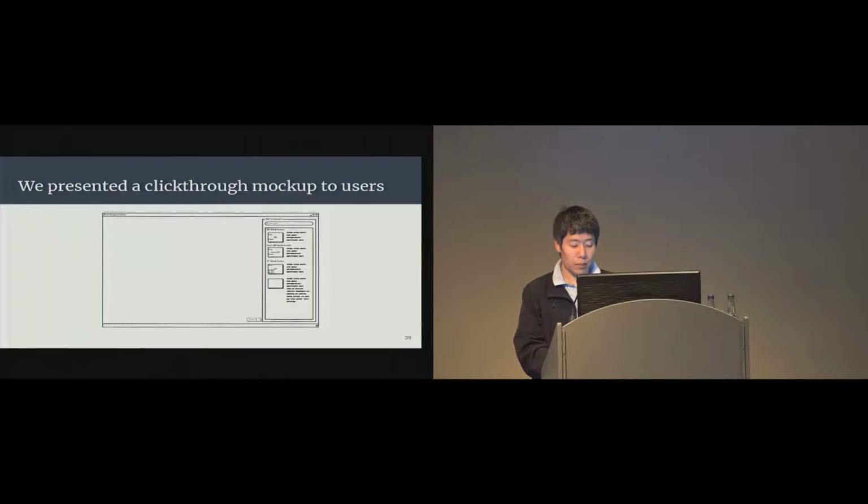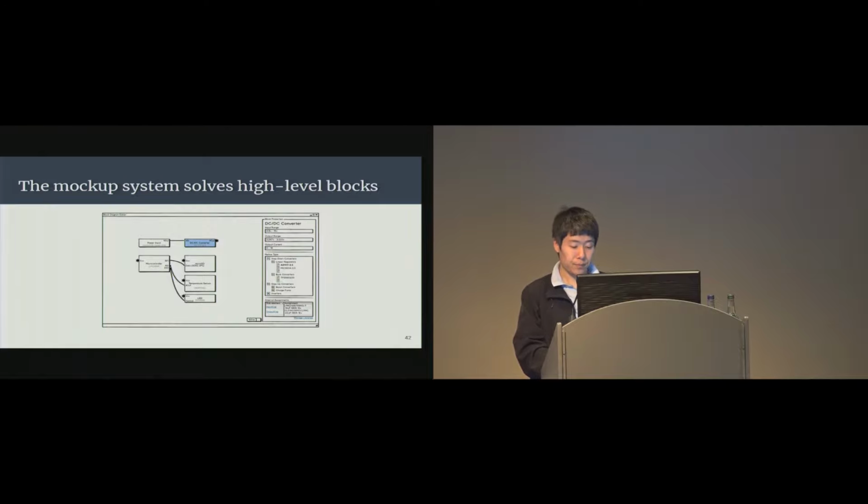These mockups started with an empty canvas. Then we showed adding one part interactively. And then we fast-forwarded to the system architecture diagram that you've seen already. The system would then solve this design by choosing concrete implementations for the high-level blocks, like we did for a step-down converter. And at this point, the design is functionally equivalent to a full schematic, theoretically exportable to a layout tool. In the interface, the right pane shows details of the selected block, including parameters to convey the parts model, and a listing of refinement types to indicate the solution space.